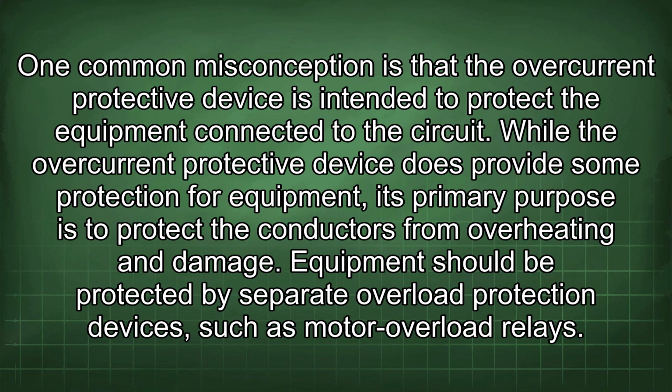While the overcurrent protective device does provide some protection for equipment, its primary purpose is to protect the conductors from overheating and damage. Equipment should be protected by separate overload protection devices, such as motor overload relays.